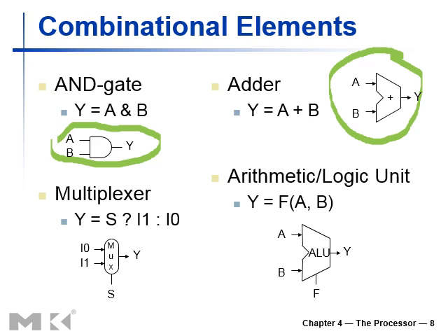Now coming to the multiplexer, how are we going to represent that as an expression? Y is equal to s basically depending upon the two inputs, and in this particular case we've got I0 and I1. These are the two input lines, and s is a selection criterion that is used to select when Y is assigned I0 and when Y is assigned I1. So this is a conditional expression here, and if that condition is satisfied, for example, if s equals 0, then in that particular case Y equals I0, and else Y equals I1.